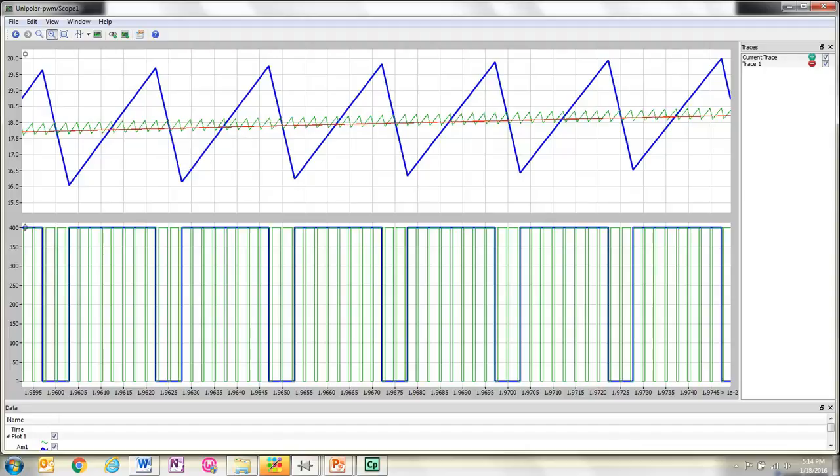So what this means is that for a given THD specification, the total harmonic distortion specification, we can reduce the size of the output filter by almost 10 times to meet the same specification. So that results in a large savings in the filter size and cost. The lower waveform shows the PWM waveforms applied to the filter end, and you can see the 10 times higher pulses in the second case compared to the original, the blue waveform. So the motivation for high frequency switching is clear.